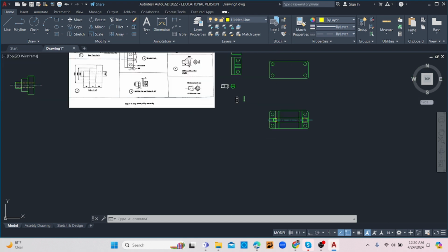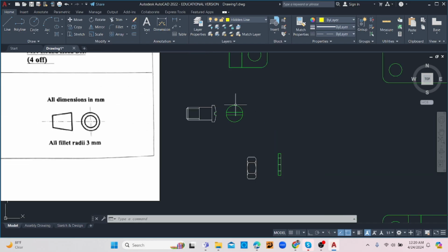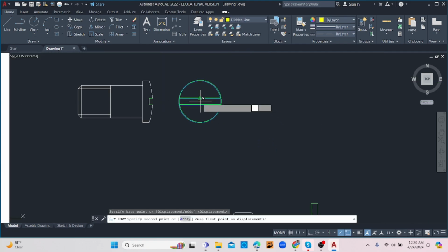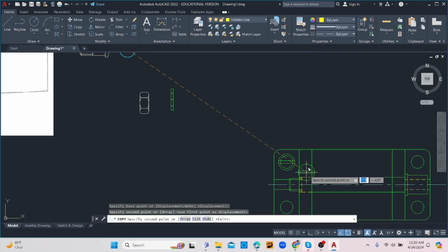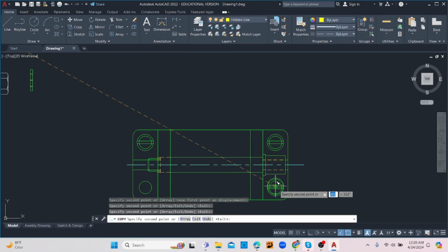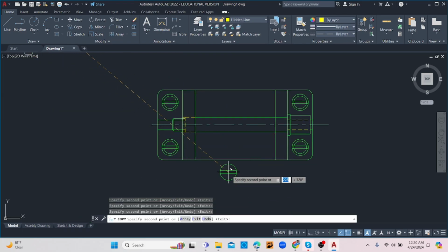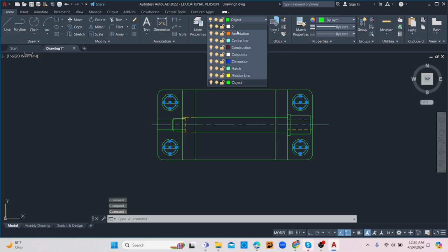So once that is in place, we can now add our screw here, and we're copying with base prime in the center, and we're placing it where these bolts should go, because they're going over all points there. Now notice what is happening now. The hole that was there before, so what is going to happen now is that those lines are now going to become what? Hidden detail, because they're now invisible.